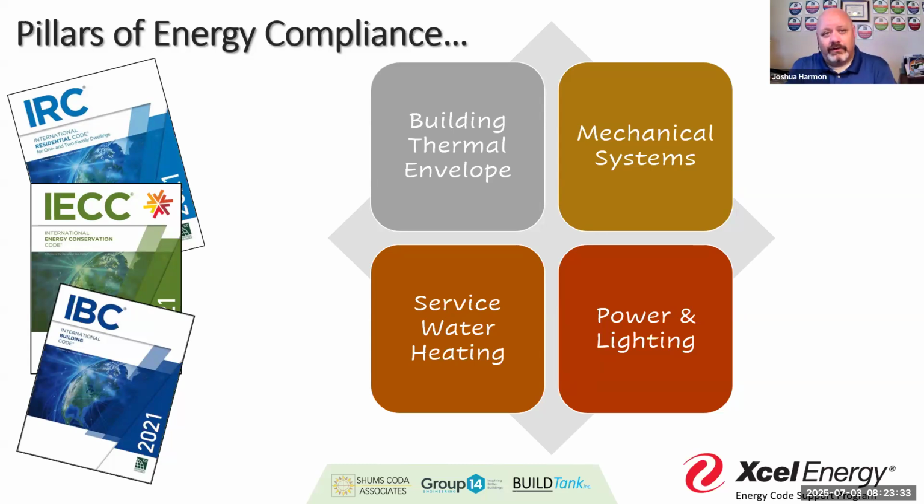they're all alternatives. So in that scenario, one of the suggestions was, then you're going to need to do a performance rating. If you are convinced that you are not putting any insulation as required by your code and by your climate zone, then go with a performance rating. Because remember, with those performance ratings, you can trade almost everything away. You're just comparing how that building's going to operate.